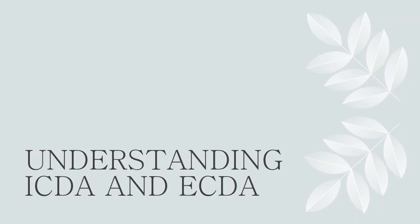What are ICDA and ECDA? Let's look at what ICDA and ECDA are. ICDA focuses on internal corrosion, while ECDA targets external corrosion. Both methods use structured processes involving data collection, analysis, and targeted field validation. Instead of inspecting every inch of pipe, they identify and examine the most susceptible locations, making them efficient and cost-effective.